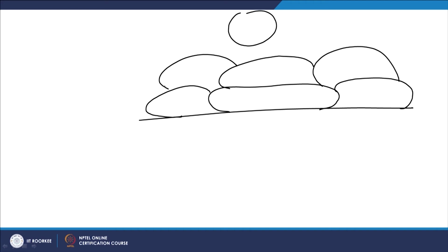But since the molten metal particle will be at a higher temperature and it will be interacting with the other gases which are present all around the molten metal particle or the partially melted particles. So, there can be interaction between the gases and the metal material of the feedstock, and that will be leading to the formation of undesirable chemical reactions resulting in inclusions within the coatings. So, these inclusions